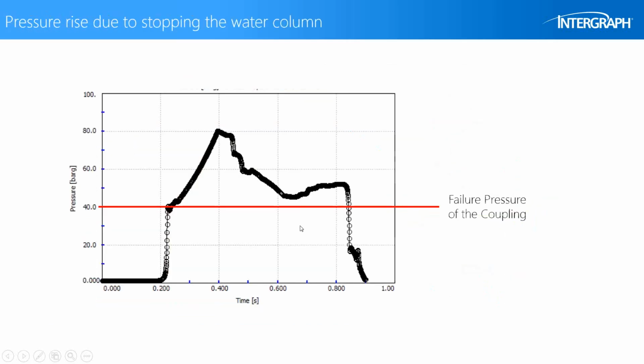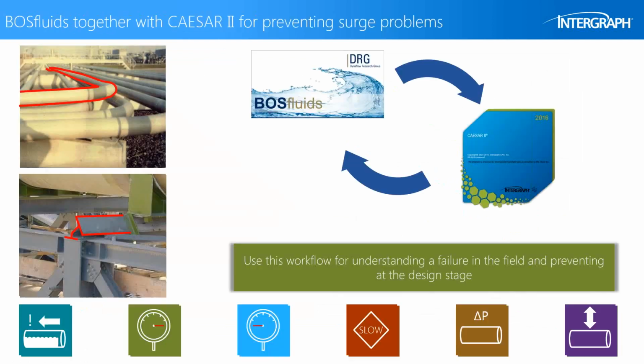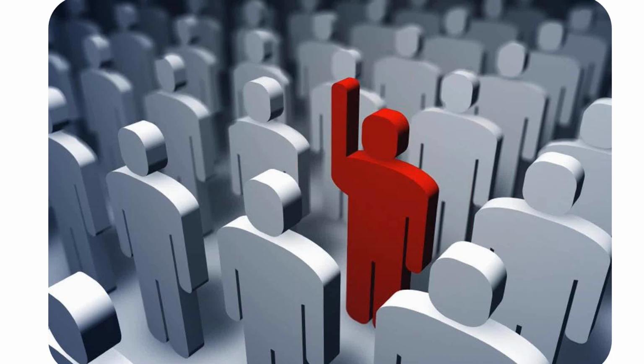And also as much information as possible about the valves. And most importantly, the flow rate and the actual pressures in the system. That's important to note, not necessarily the operating and design pressures you get from your isometrics or specification sheets, but actually the pressure that's arising in the system. If you remember from the system we showed you previously, there's quite a long system to that location of failure, and the pressure differences through the system would have a significant impact on what the pressure is and what the resulting pressure wave would be.